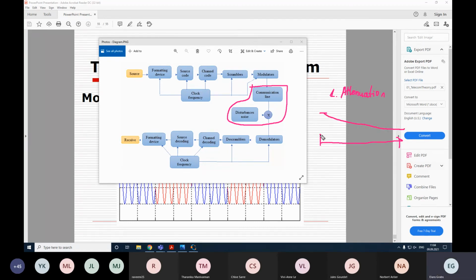There is also a noise, which is not that strong by itself, but once your signal has been weakened to some certain point, this becomes comparable with noise, and that is when this noise can actually interfere with your signal and make errors. And this noise is actually the reason why we have these errors, for which we need Hamming code to correct them and Interleaver to improve this correction.